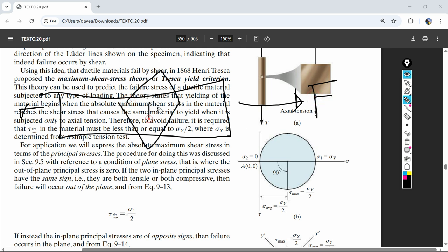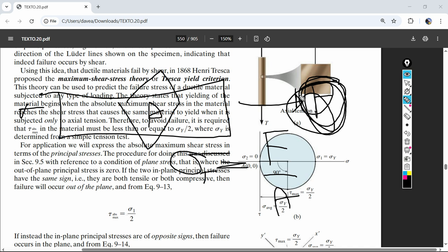This thing has a cross-sectional area. You know that area, and so for the stress, the tensile stress is going to be force divided by area. With the machine, you're increasing this number, and you've got a gauge on it, and you're getting this graph to plot. It's a straight line, and then all of a sudden at some load or force divided by area, it starts to yield. A very simple tension test is getting that number, and we would call that sigma T for tension max.